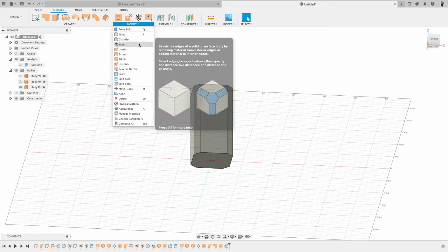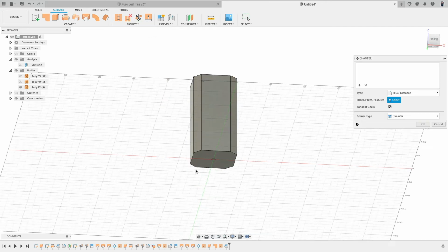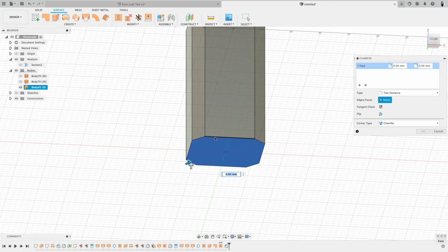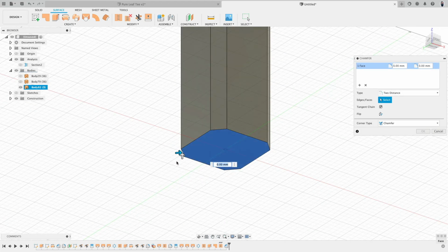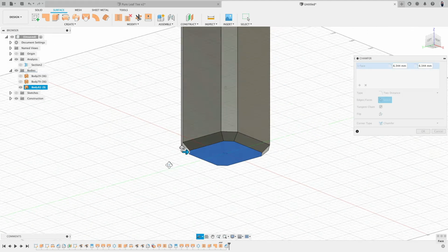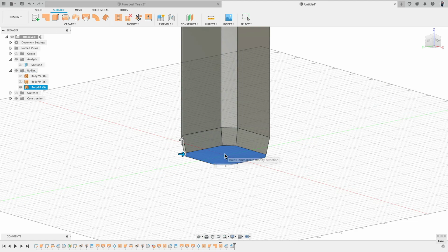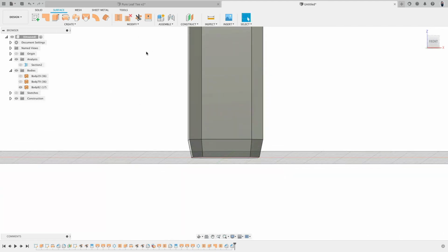And then one more time a chamfer along the bottom here, but this time we would like to set it to distance one. I selected the face because then it selects all the edges, and then this actually goes inwards and then this goes upwards. And you see how this way we can play with the flow. Pretty nice actually. 15 and this 5, 3, that's good. Very good.